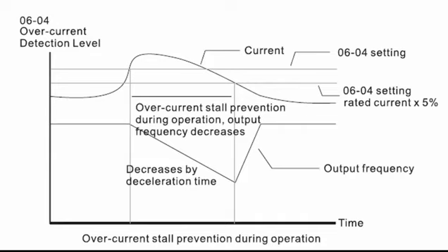These are applications in which if you increase the speed, the load also increases. Actually, it's not proportional, it's quadratic. It does not work in constant torque applications. In conveyors or other similar applications, it makes no difference if you decrease the speed. The output current will not really decrease that much. So keep in mind that this function can only be used on variable torque applications. Okay.